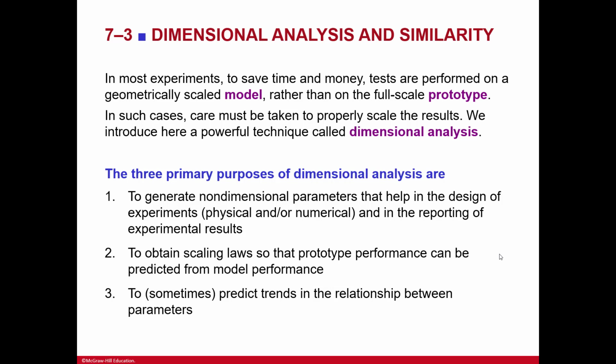So once you progress past that CFD analysis, because you can only get so much, though it's quite a lot that you can get out of a CFD analysis, the next step, in most cases, to save time and money, is you do a geometrically scaled model rather than a full-scale prototype, right? So you typically do a CFD analysis, and then you do a scaled model, and then you move on to a full-scale prototype.